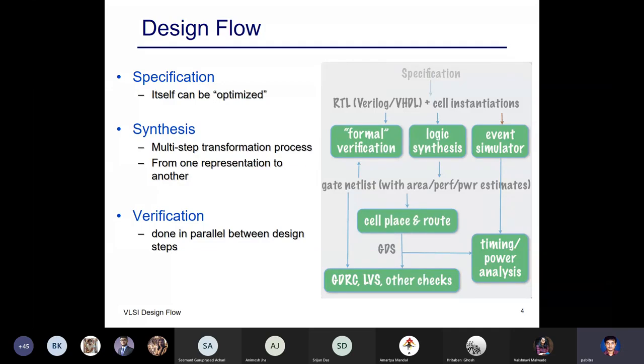So what happens after you have written a Verilog description? Suppose you have a piece of hardware, you have a structural description or a behavioral description of the hardware in terms of Verilog. Now, as if your FSM or whatever you have drawn before, it's now a program in a language, or a description in a language. So now, what do you do with this description? As I have said before, you can do two things. Either you can do synthesis.